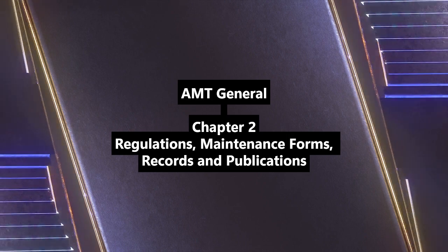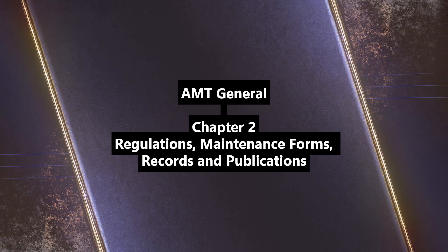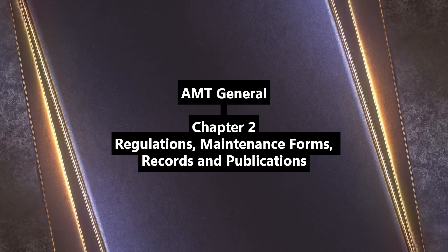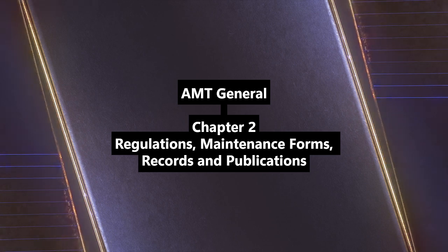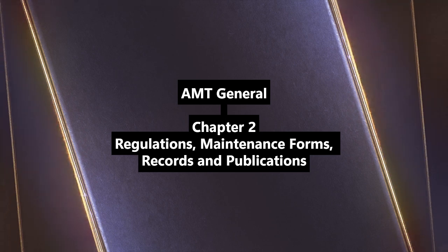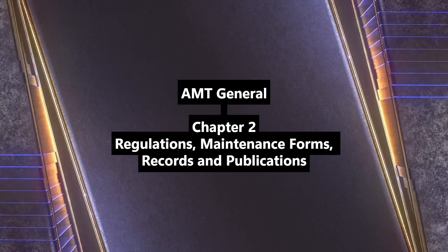And for mechanics, which parts of 121 are most relevant? Subparts J and L. They cover special airworthiness requirements and the operational manual details: organization, inspection personnel, maintenance procedures, record systems. And aging aircraft. Yes, Section 121.1105 has specific aging aircraft inspection requirements.